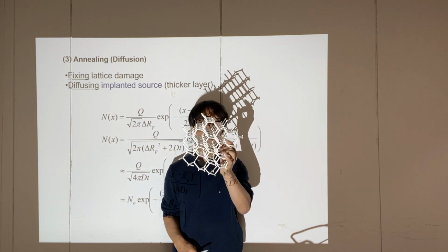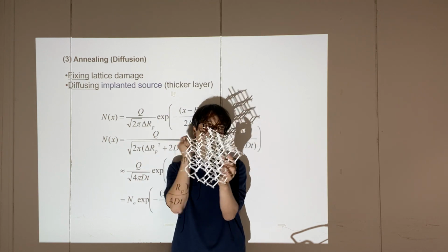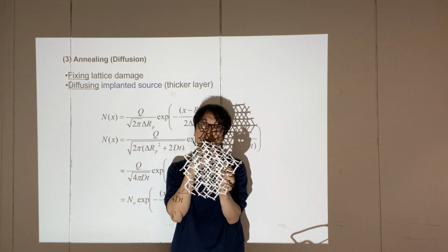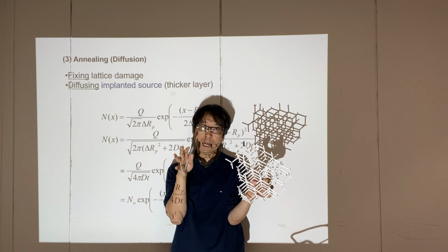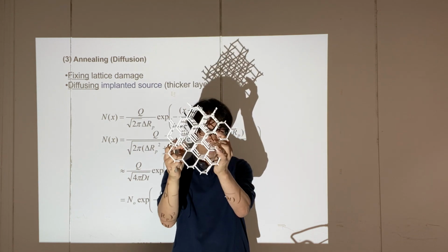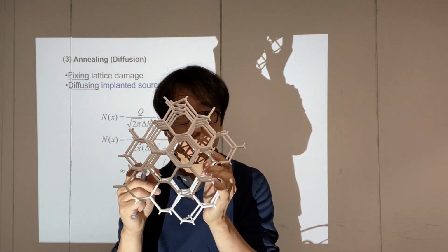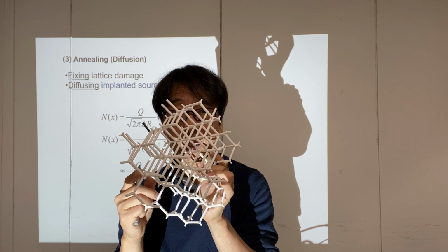So in order to avoid such a problem, let the particles hit the lattice and scatter nicely and form this nice Gaussian distribution. They will tilt the wafer a little bit. So not this perfect orientation, but tilted a little bit.